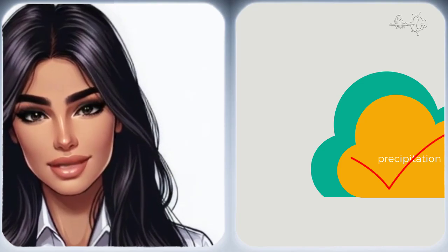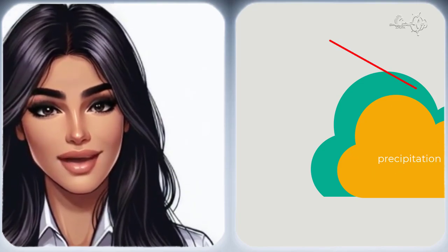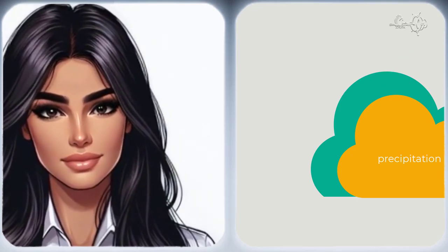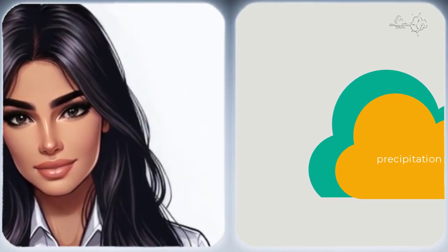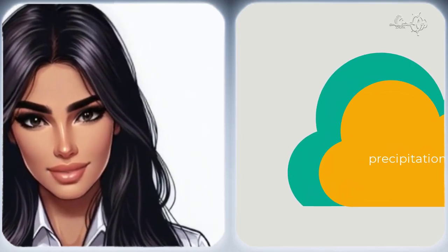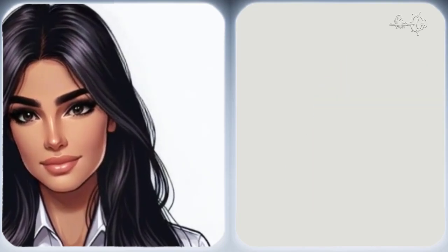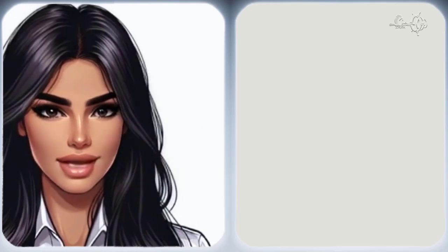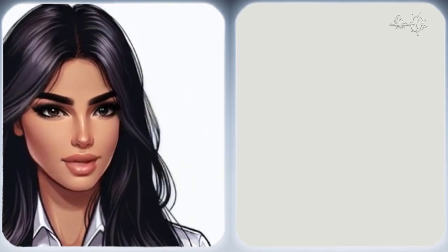Note that the radar can only detect precipitation and not the top of the clouds, which may extend well upwards. In addition, with severe weather, the cloud may grow at thousands of feet per minute, and a turbulence bow may be expected above the cloud tops. That is why it is generally safer to deviate upwind and sideways of weather rather than attempting to overfly weather.